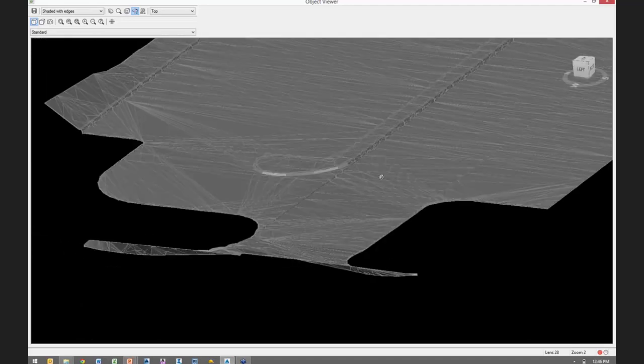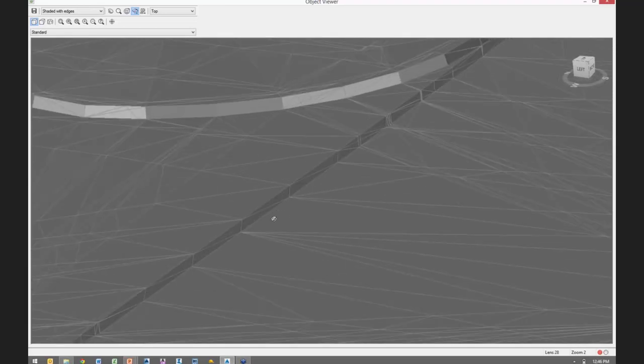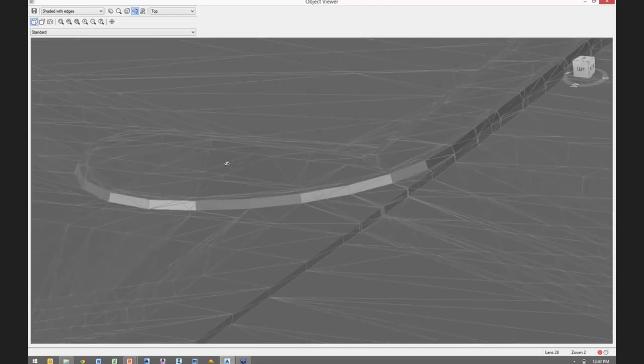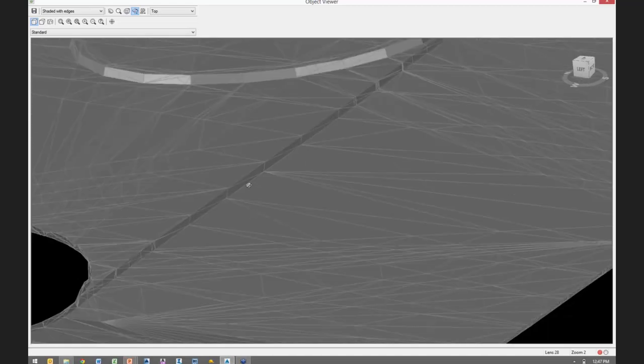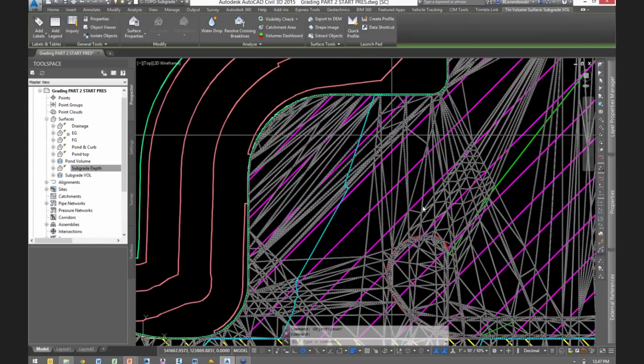Remember we said that drive right through the parking lot was heavy duty pavement? My subgrade goes down 1.5 feet right here. It goes down 1 foot right here. And here, that's 1 foot as well, but we could have gotten more detailed with our subgrade depths if we wanted, and we could have put a 6-inch polyline there to represent perhaps 6 inches of topsoil. So this is a subgrade surface that we can now use to calculate quantities from.